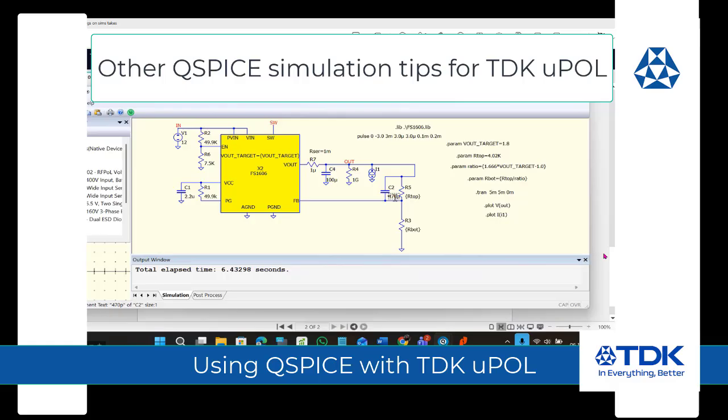This is a fast forward capacitor for the output, and my experience is that if you increase this capacitor, you would improve the stability of this whole thing. Normally you shouldn't have to. The output in real life will not break down on you, but we're dealing here with a simulator, and there are some bugs to be resolved.